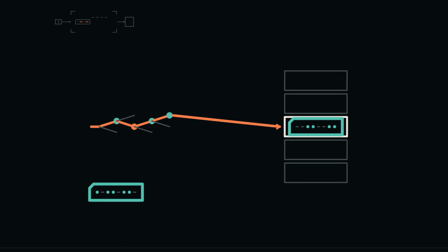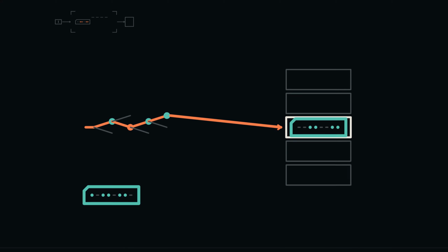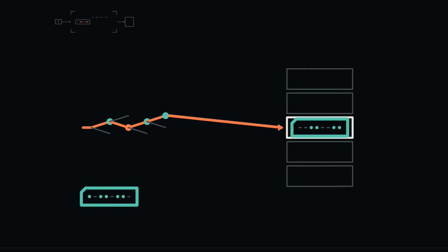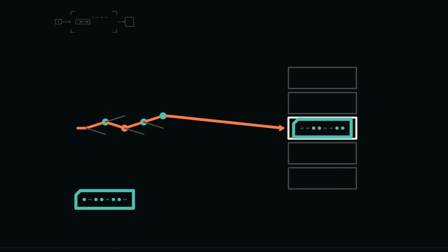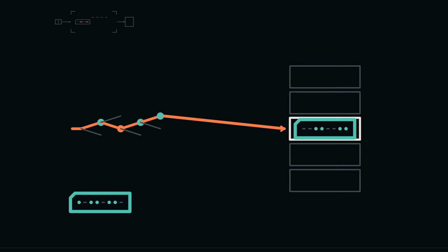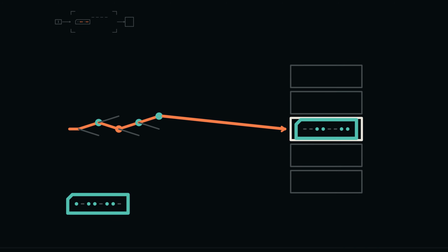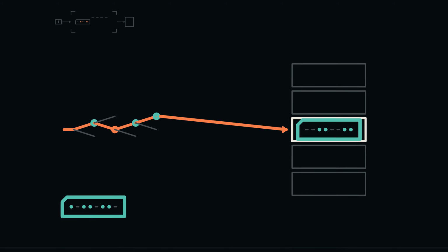A decoder turns the compact address into a one-hot selection. For every legal address, exactly one output is active. With 3 address bits, pattern 011 activates output 3 and leaves the other 7 inactive. The decoder does not carry the byte stored in register 3. It produces only the permission signal that identifies register 3.